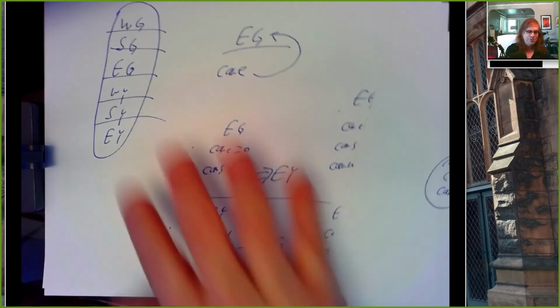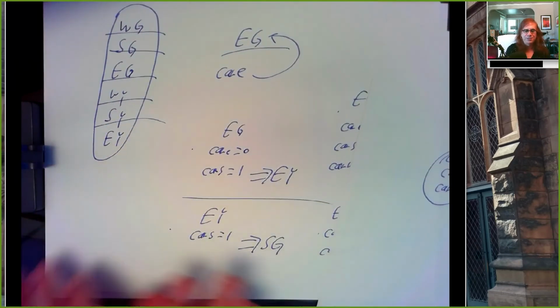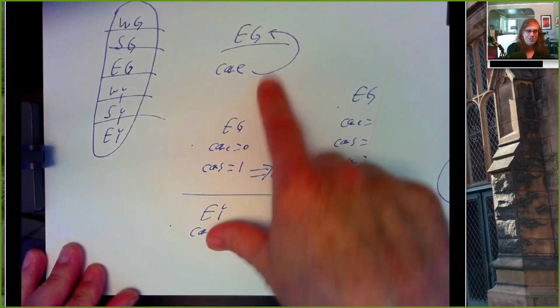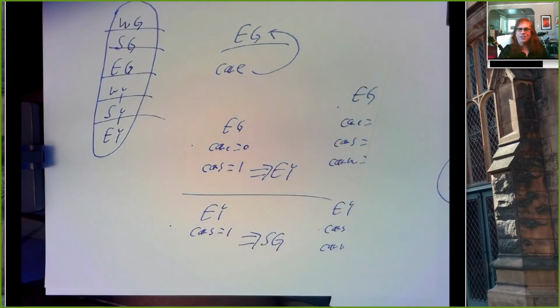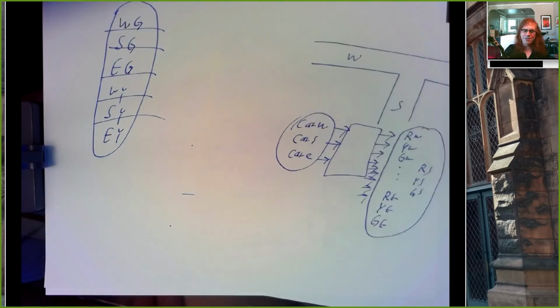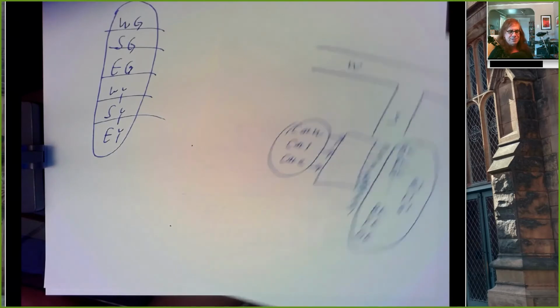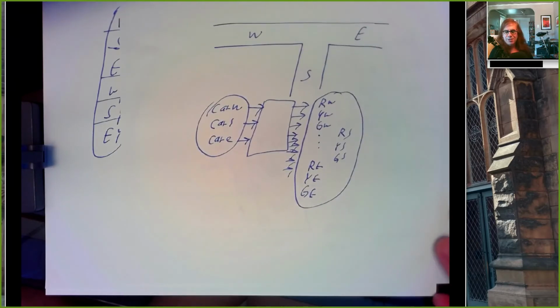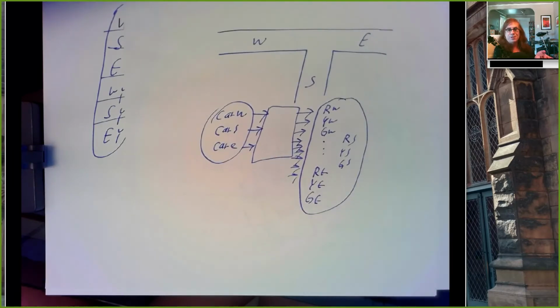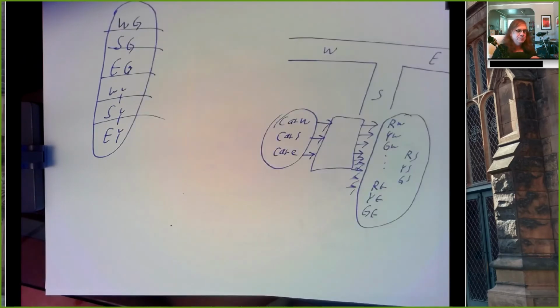And if you work through it like this, it turns out to be a lot simpler. Because, for example, if there's a car to the east, we don't care about the other cars, right? If there's a car to the east, we want to respond to that. We'll look at this in Aldec and get some ideas on how to code these things up with if statements or with case statements, which can save us some logic.